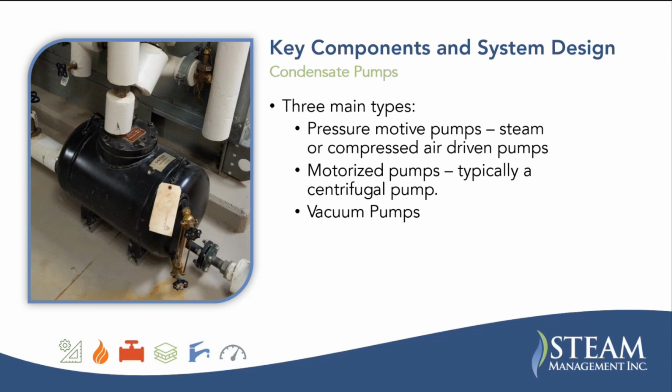Motorized pumps is a typical centrifugal pump. You'll have a condensate collection tank, and then downstream of that, you'll have a pump set, and it'll just pump the condensate to the next tank or to the deaerator, typically.